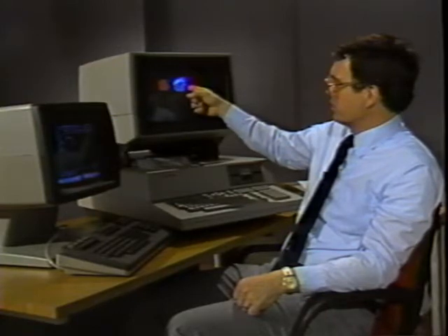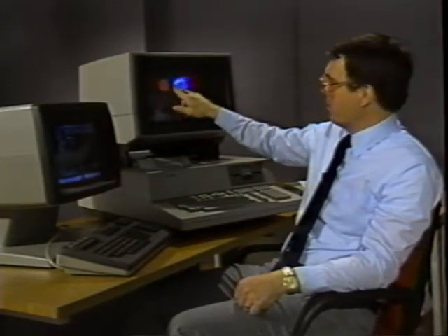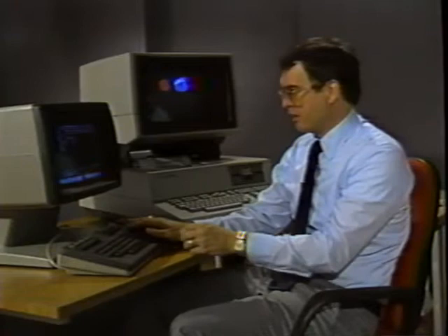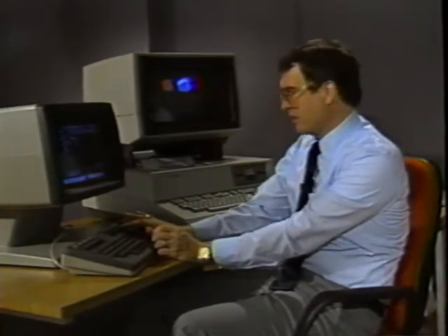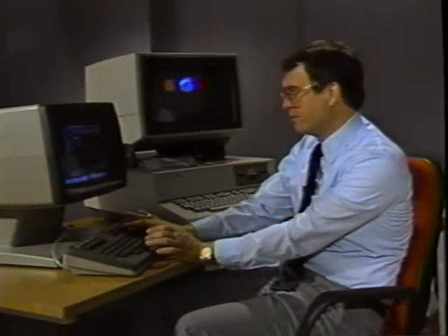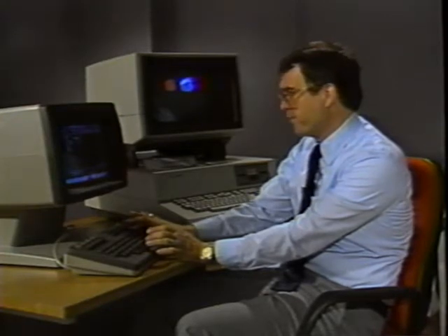The software command that I give to perform this subtraction is called an intersect command, in which I give this object here a positive sign, and I give this object here a negative sign. I combine the two together and get the finished object. Now let's look at that graphically, and then we can look at the object in finished form this way.